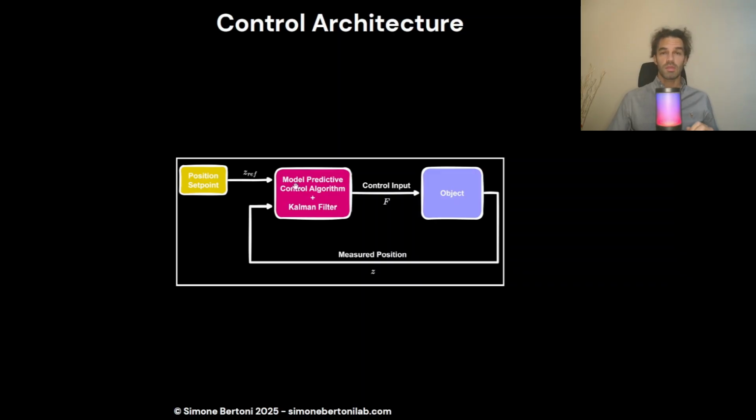Remember that in MATLAB, for the linear model predictive control, which is what we're doing now, we get for free a Kalman filter in the implementation, because we always need a state estimator with model predictive control, unless we measure all the state, which is possible in our simple examples, but is probably unlikely in reality.